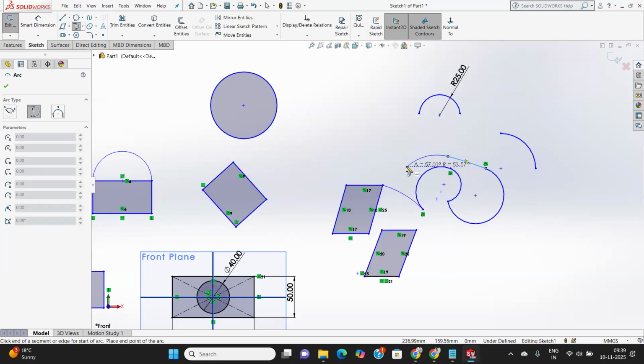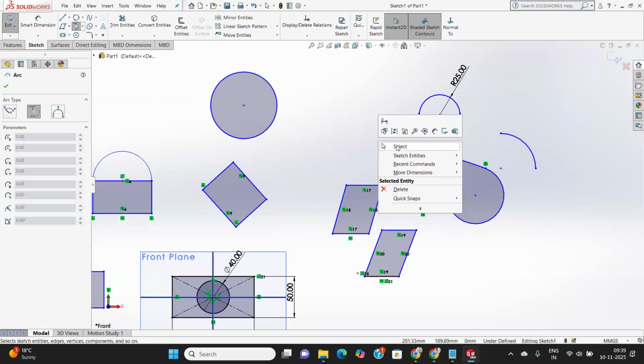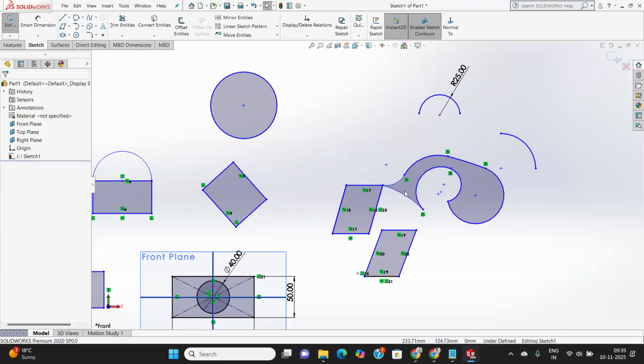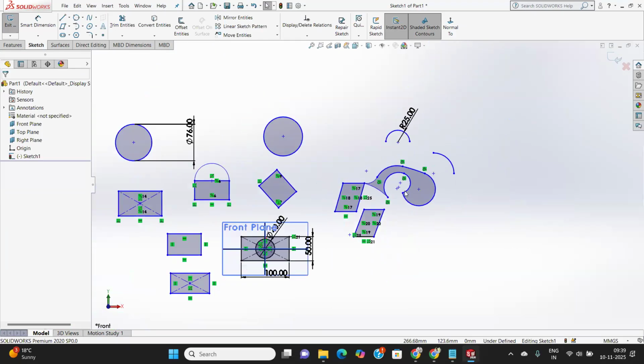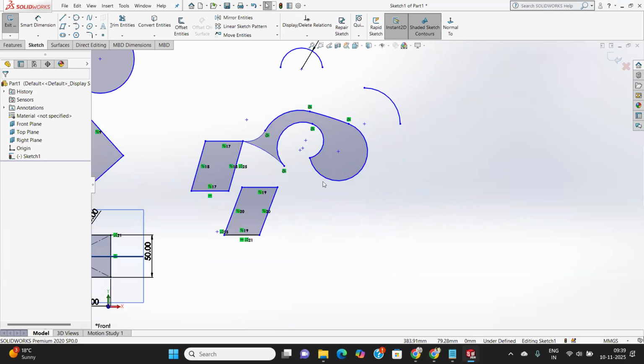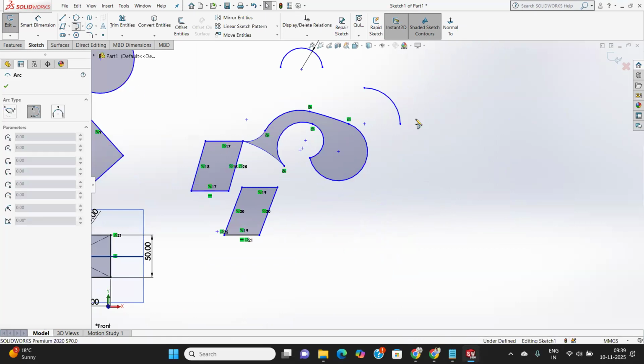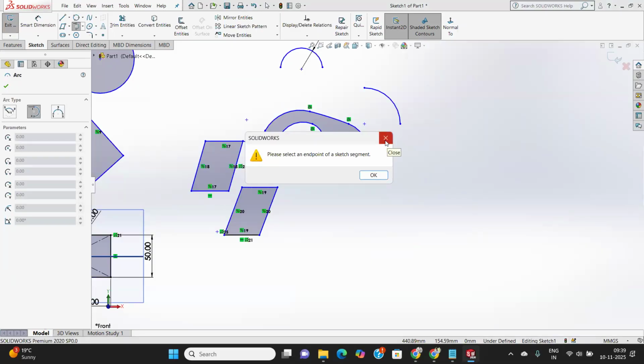This is called a tangent arc. It is just used for making this type of thing look better. Tangents always make the points, from one point to another. If you click anywhere in a section where you don't have any points or drawings, then this will not work. Always remember the tangent arc always needs existing object points.